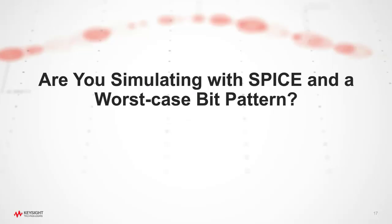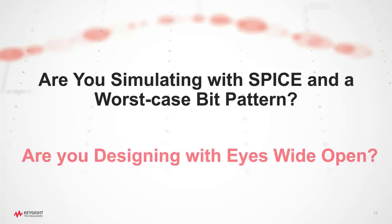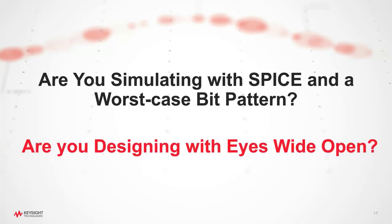So, are you simulating today with SPICE and a worst-case bit pattern? Because as DDR speeds reach the top end, there are many more bits in flight, there's more crosstalk, and determining the worst-case bit pattern that will give you the maximum eye closure becomes exceedingly difficult. And not only that, it doesn't account for the long tail of the random jitter. So, without something like a DDR bus simulation, are you designing with your DDR eyes wide open?